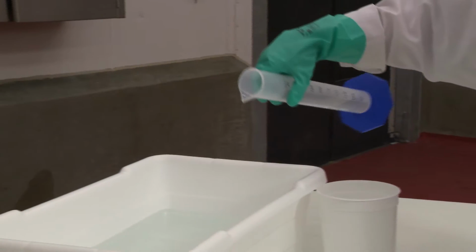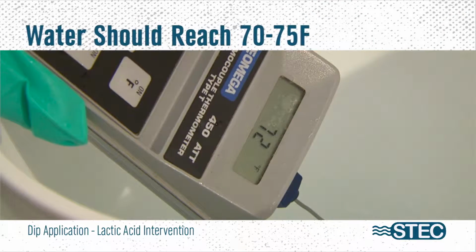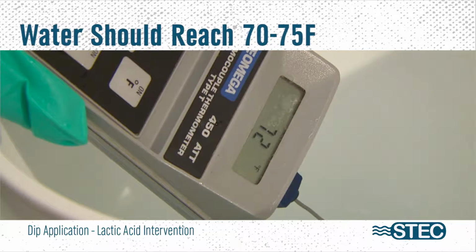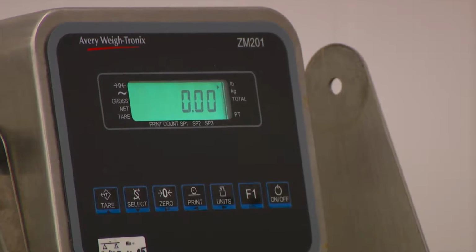The lactic acid solution should be mixed as close to the time of use as possible. Before adding water to the mixing vessel, it is important to make sure it has reached the proper temperature. Allow the water to run for several seconds before adding water to the bucket or tub. The water will be weighed to ensure the accuracy of dilution.